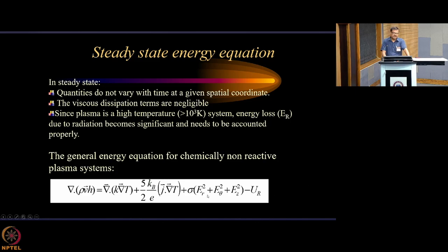One is your finite difference method, which is very simple, and you know that concept, and even though it is very simple, it can actually give you very accurate results. No need to neglect this technique, finite difference, saying that it is very simple. Of course, it works for simpler geometry. If you have a complex geometry, then handling those systems using the finite difference technique is a bit cumbersome. But in geometries where it works well, it will really give you accurate results.